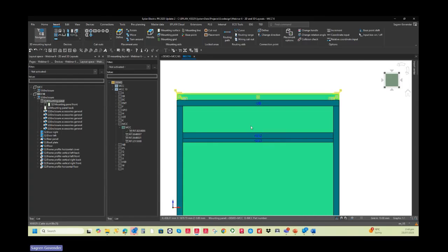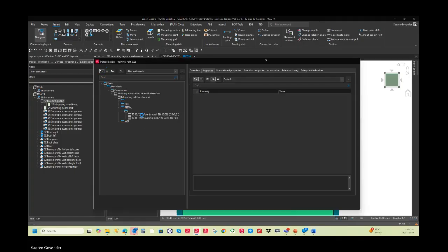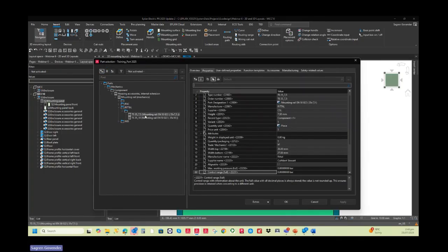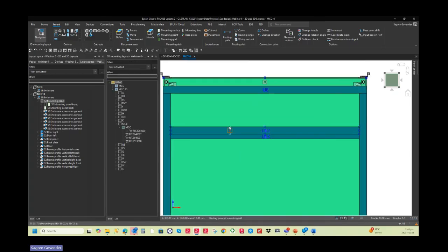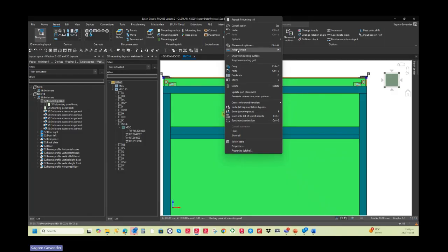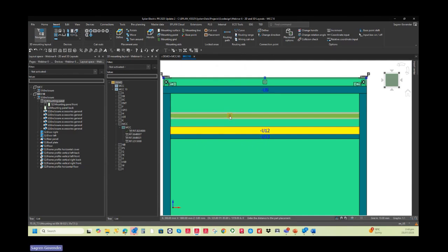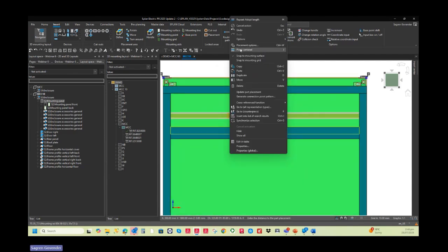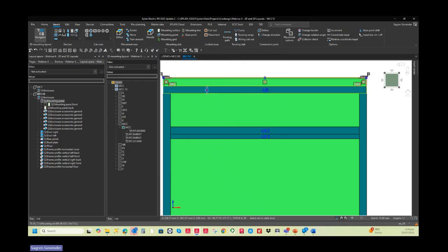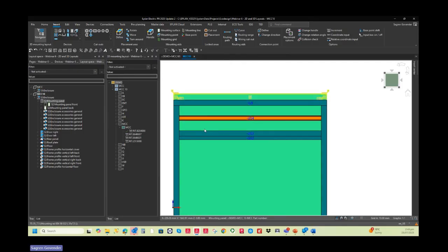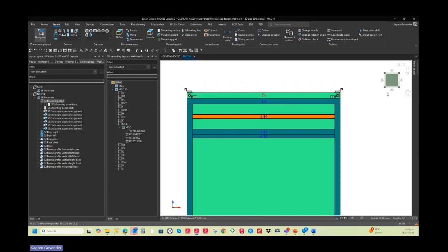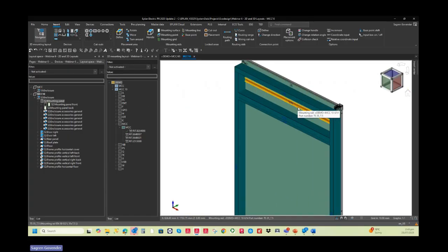And what if I want to place a DIN rail in the center here? Real easy in Pro Panel. If I go here to my mounting rail, again, these parts are available in the data portal. I've got a DIN rail in there. I'm going to go OK. And if I right click, I can now adopt the length of this trunking. And if I right click again, I can say place center. So if I choose the trunking on the opposite side, it's going to place it in the center. Real easy. So let me go into my isometric view, and now you can see this.